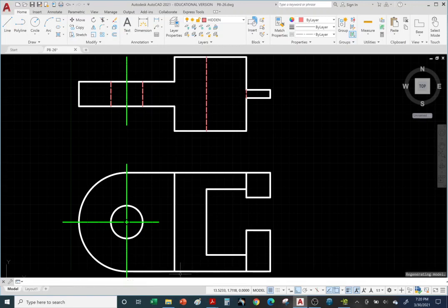Ta-da! You blinked, right? Okay, if you want to increase it some more, we can type in LTS again. LTS, enter, and let's increase it to 2. See what we get from 1 to 2, and don't blink. And 3, 2, 1, don't blink. Enter. Okay, maybe that's a little cleaner, right? I'll leave it up to you. I'll let you play with the LTS.